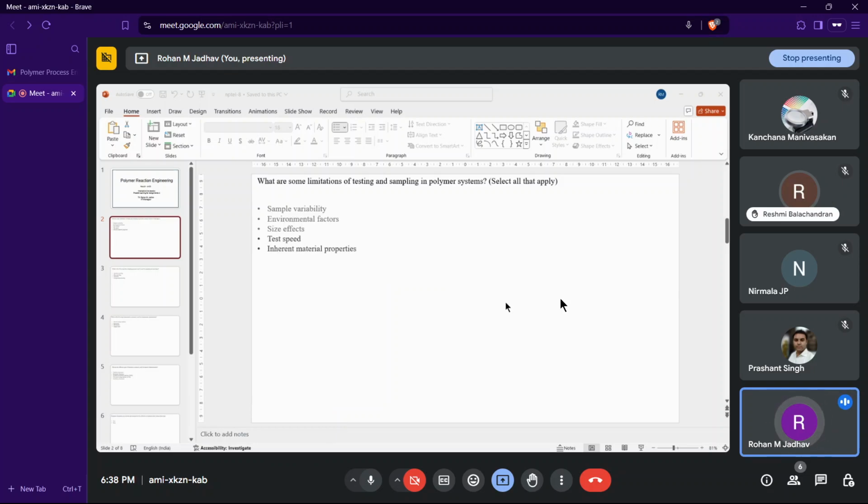In injection molding, you are sending the material through the screw, and it is coming out at the other end from a singular opening. That is the gate. So some would say that injection molding is a direct shaping process, but extrusion is also in some manner a direct shaping process because you can change the die shape and get the direct shaped material. For example, if you want to make a cylinder of X diameter, you can get your material extruded out from a die of that X diameter, and you will have the sample ready directly.